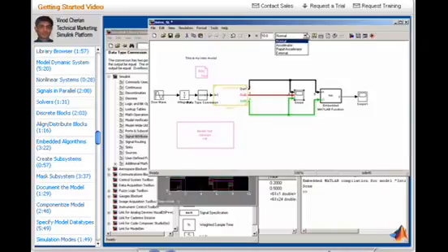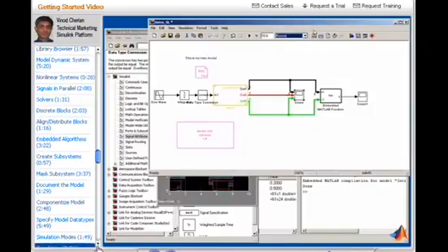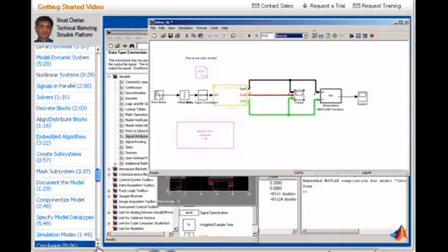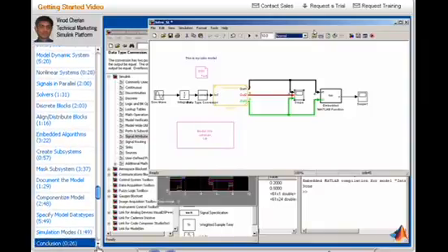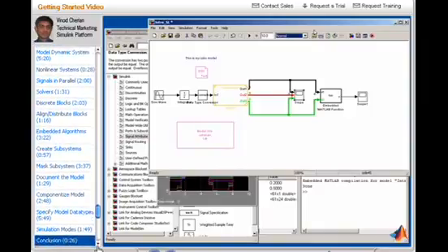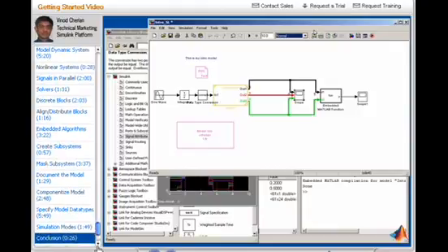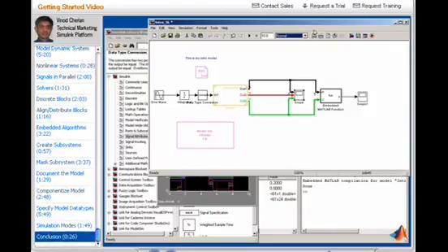So there you have it. In this session, we've created the model of a hybrid system, incorporated existing MATLAB algorithms into the Simulink model, componentized that model, optimized it for fixed point implementation, and looked at the alternative simulation modes that Simulink offers.